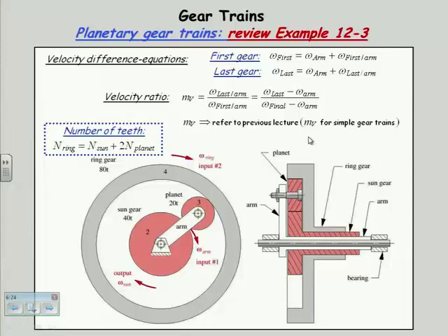And this is the principle on which the automatic transmission for automobiles and trucks is based. The gears are always in mesh. You don't have to shift them in and out of mesh. And I can have a variety of ratios, including reverse. Recall Ferguson's paradox, where I showed you how the same gearbox could go both directions simultaneously with enough sets of gears. So these are very, very useful devices.